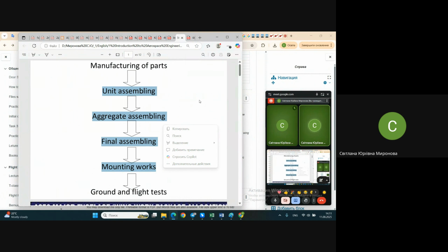Next, I will talk about it, and you understand that assembling and mounting work are similar by their inner context. But assembling, we call a locating process. Assembling is a process of locating, temporary clamping, and final joining of assembly components, of elements of a structure or some product or whatsoever. And mounting is a process of locating, temporary clamping, and joining of assembly components at the place of their future operating. So the difference is that assembling we understand as creating the whole device, the whole vehicle from pieces.